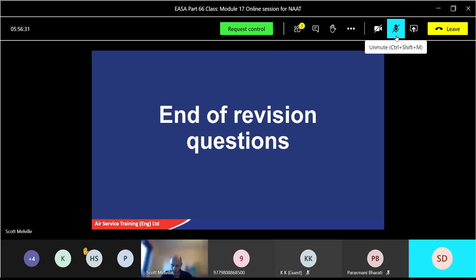Probably the note on page 41, minimum constant speed is the minimum RPM selected by the PCU and allows rapid acceleration. So on page 41, it might be worth highlighting that one with reference to control. Minimum constant speed is the minimum RPM selected by the PCU and allows rapid acceleration. It's got a note just underneath the diagram. It says a note. Probably highlight that one.